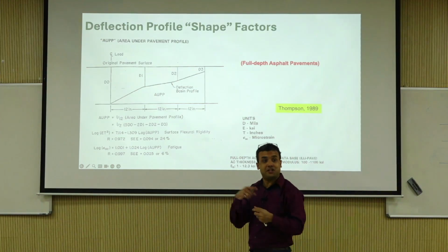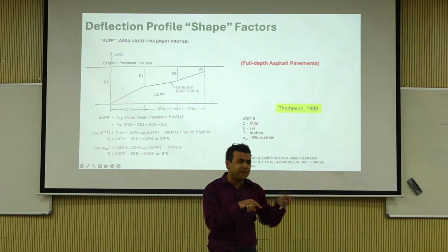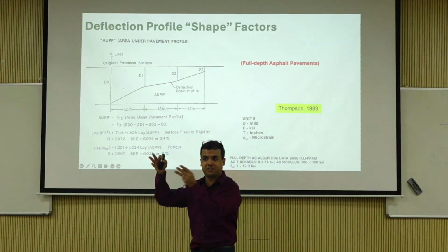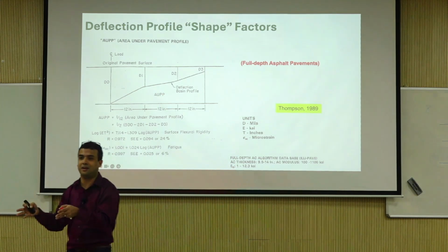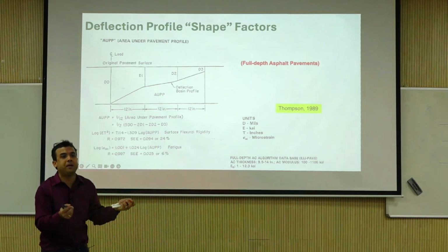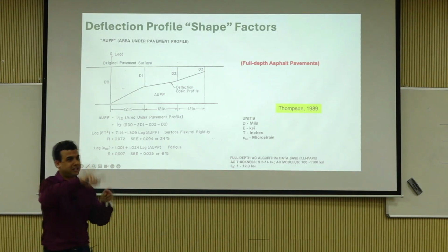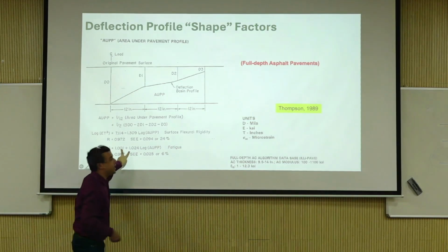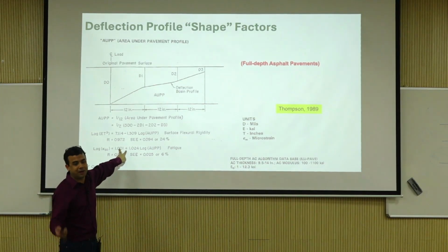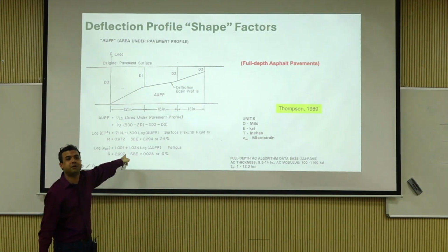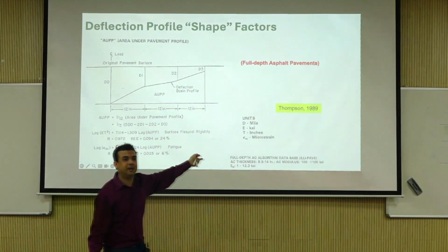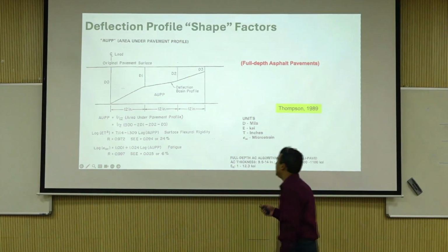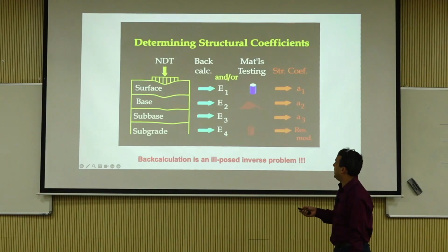Now, if as a researcher later on you track the source of this, you go back and realize this is all based on extremely heavy finite element coding and modeling. But the practitioner is not being bogged down with all of that. They just have curves or simple equations. Like this fatigue equation is probably based on, I don't know, maybe 250 FWD analyses or even more than that. It's just in the background. But the bottom line is, this is still valid for the areas that they considered.